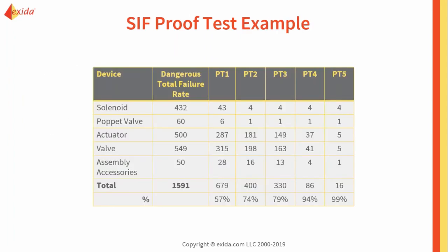Once again, I really like examples, so I wanted to take some numbers and put them into real life cases and real life SIF. So I put together just a pretty simple SIF. We have a solenoid, a poppet valve, an actuator, a valve, and some of the accessories put together. And we did FMEDAs for all of these cases.